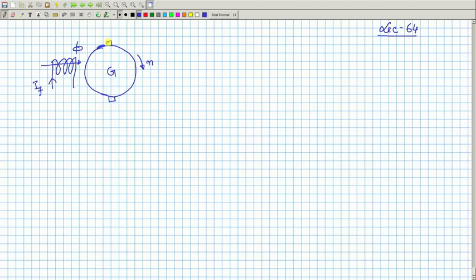Anyway, we found out that if this is rotated, in this case, the voltage across the armature terminals A1, A2 under open circuit condition, if I say generated EMF E g, it is given by P z by A phi into n, so much volts, if phi is in Weber and n is in RPS. Do not forget that. Of course, it can be changed to RPM. And another thing is